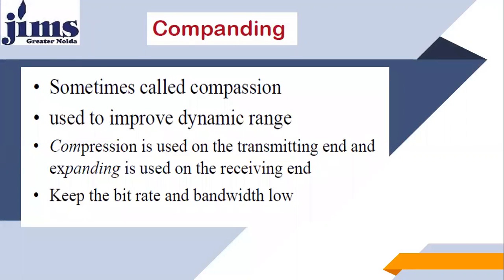So, the percentage of error is more in low voltage levels as compared to high voltage levels, because 12.6 is approximated as 13, so it's a difference of 0.4 volt, and 1.6 approximated as 2 volt, again we have a 0.4 volt difference, but that difference is more significant in the case of 1.6 volt rather than 12.6 volt.